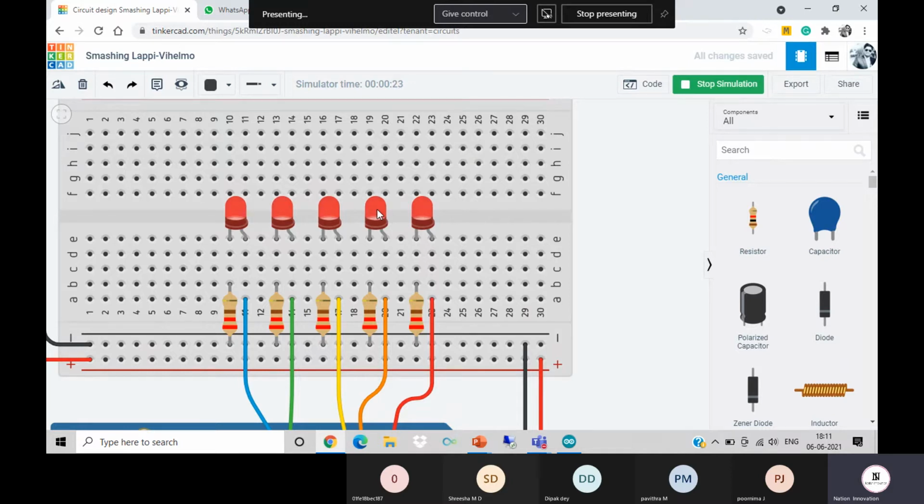Fine, everyone. So this is how we interface an LED with the Arduino. Now, when we interface a relay as well, 90% of the thing is the same, just the connections are different. The code remains the same. You can do everything you do with the LEDs except the PWM functionality, because some relays are not that fast to operate. Fine. This is the main reason.